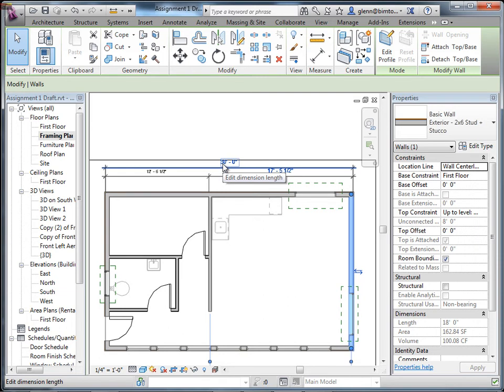We tend to buy materials in either 2 foot or 4 foot or even increments. So if you can kind of make everything more even, better. In fact, the way this dimension will probably get determined is someone's going to go out there and pour a concrete slab, and when they pour that slab, they're going to measure out 30 feet. They don't want to measure 29 foot 10 and 5/8. Okay, then they'll build the walls on top of that.